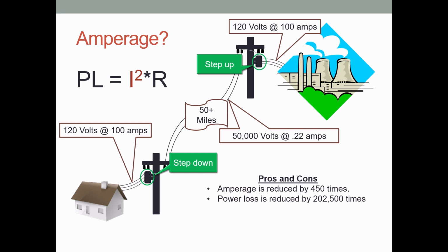The one disadvantage to this transmission scheme is the wire carries a high voltage. The high voltage requires a thick insulator on the wire and/or power poles that need to be tall and have heavy-duty insulators to isolate the wires and protect the public from electrocution.